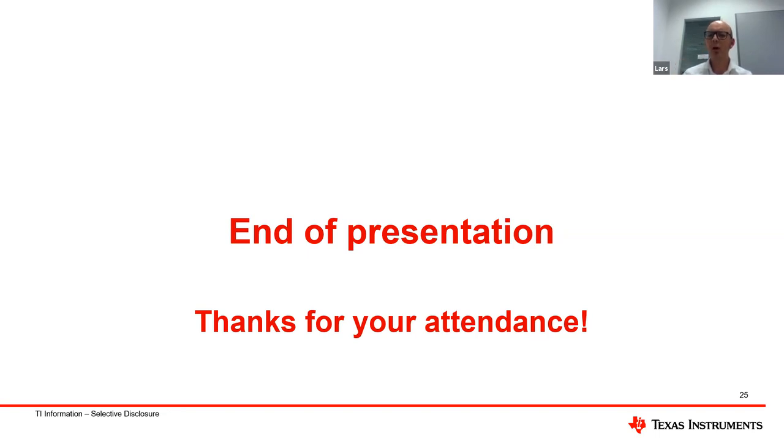Then I think there is at least one multiplexer which is functional safety capable. And then you open the document and you see the failure modes, and then you get an idea what failure modes a multiplexer can have. Then you actually address them. For example, my diagnostic 3 is stuck one of the channels. Here you can see how I actually cope with that fault type.